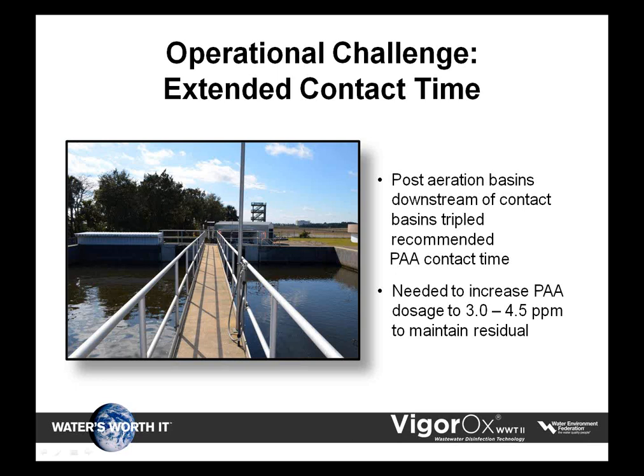Our next operational challenge was extending contact time. As mentioned previously, our plant has 2 post-aeration basins after the contact basins. Our trial study could only compare the disinfectants up to the end of the contact basins before the water combined and entered into the post-aeration basins. When we went to full plant PAA, the addition of the post-aeration basins tripled the recommended contact time. So we're having to increase our dosage to 3 to 4.5 parts per million to maintain a residual, which was double what we had used during our trial study.